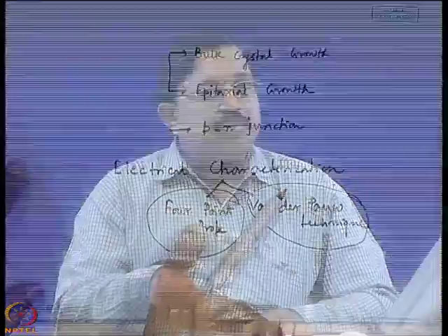As the name implies, 4 point means there are 4 platinum or gold needle-like contacts which are pressed on the surface of the sample. So it is basically a press contact, and I shall show you the attachments using which you can make contact by means of a small pressure, because it is connected with some spring attachment. So, it can adjust itself.